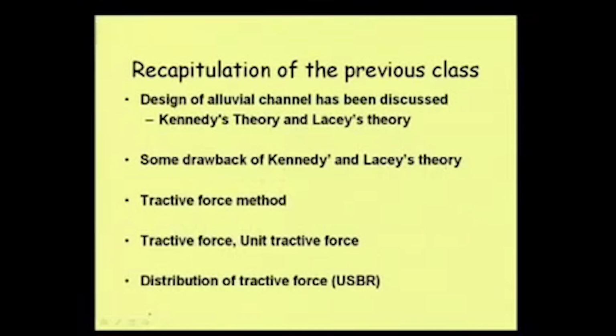Then we were discussing in the last class the distribution of tractive force. That unit tractive force was actually coming as an average unit tractive force, because we considered the force exerted by the fluid on the entire surface in contact with the water over that length of the channel, and divided it by the entire surface length in contact with the fluid.